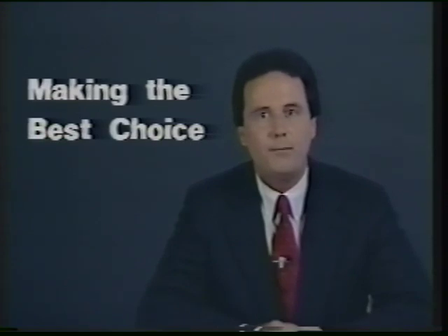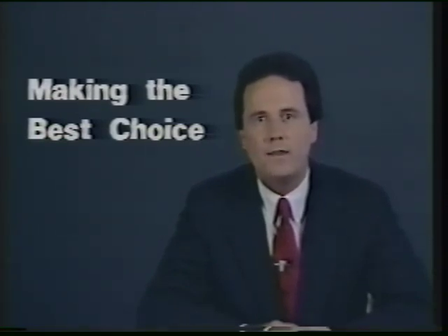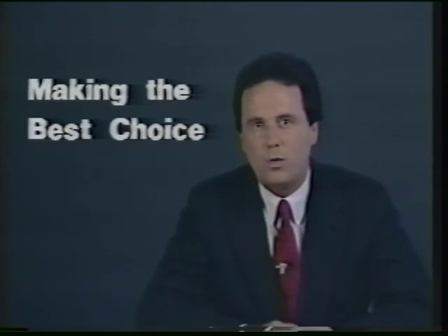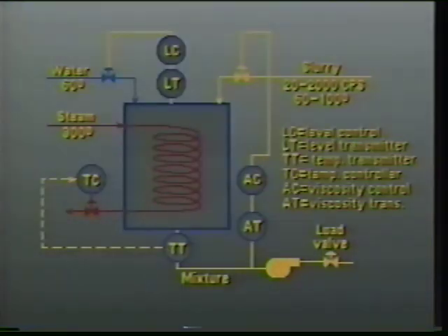As you work to find the best solution, you should bear in mind that there may be 3, 4, 5, or even more solutions that are all equally practical. The choice often boils down to the one that seems most logical and makes the most sense to you. Once you have made the choice in matching the manipulated variables and process variables, the next step is to add the appropriate instrumentation that will implement your control strategy. This includes the selection of controllers, transmitters, transducers, positioners, sensors, and so on.